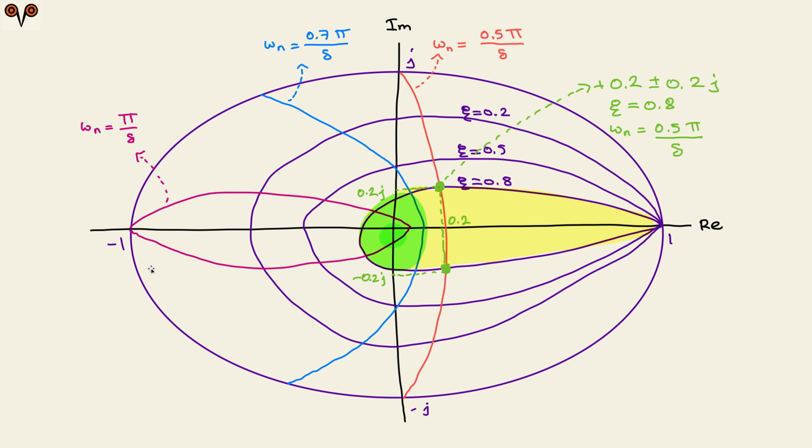So actually you can look at this nice map where we choose eigenvalues with respect to natural frequency and damping ratio. We know from the continuous time version, if your damping ratio is greater than 0.707, for the sake of this video I'm going to use 0.8, the system will not make oscillations, maybe a bump, but then it will settle down. So basically, this means that eigenvalues need to be chosen in this region of the unit circle. This is the unit circle.